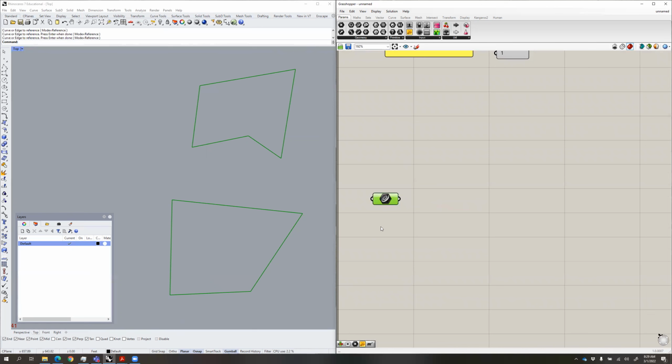If you ever select a component, you should see it visualized and turned green in Rhino. If that does not happen, check this bar right here where it controls the visibility. Either it shows nothing, which is this one right here, and then when you select stuff, nothing highlights, or if you choose the red box on the side, it shows it. And this one in the middle only shows curves and wires. It doesn't show surface geometry.